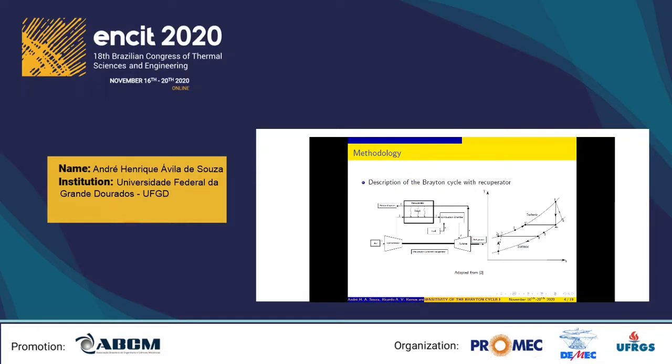The exothermic reaction releases energy in the form of heat into the cycle. Then, the combustion gases at high temperature and pressure expand through several stages in the gas turbine, producing work. A fraction of the work is transmitted by the shafts to operate the compressor, and the remaining work is the net work output of the Brayton cycle. The exhaust gases leave the turbine at atmospheric pressure, being discharged to the atmosphere, configuring an open cycle.